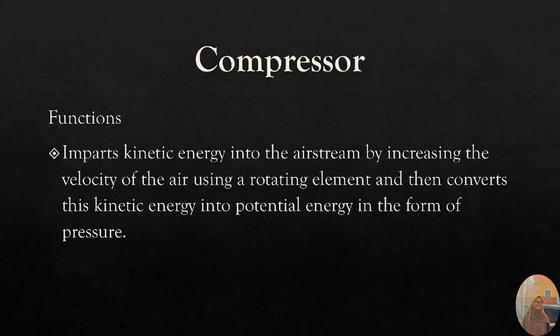My name is Nurul Khayrin and I'll be explaining about the compressor. A compressor functions to impart kinetic energy into the airstream by increasing the velocity of the air using a rotating element, and then converts this kinetic energy into potential energy in the form of pressure.